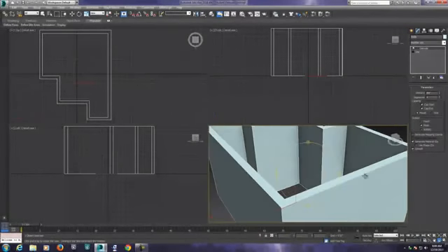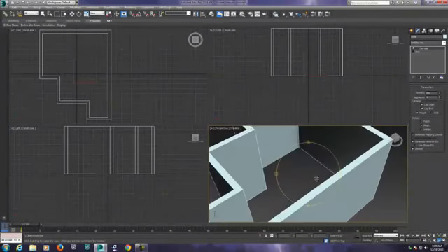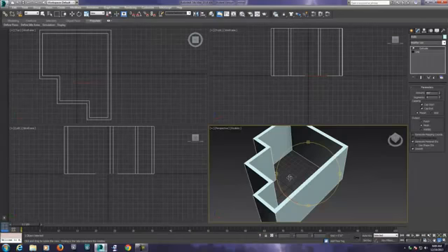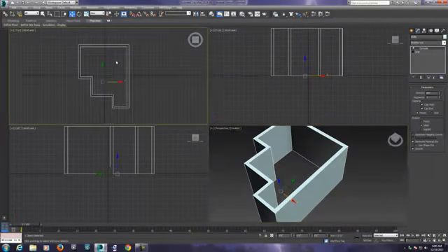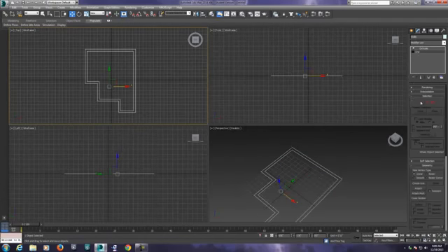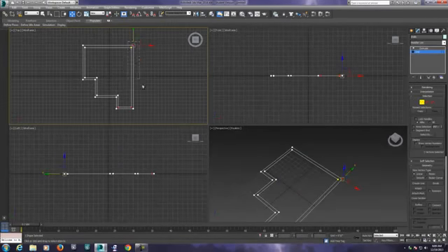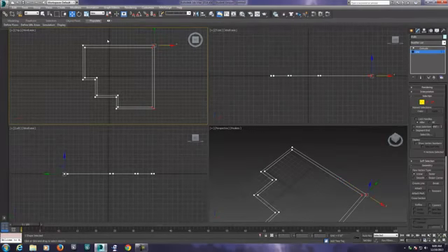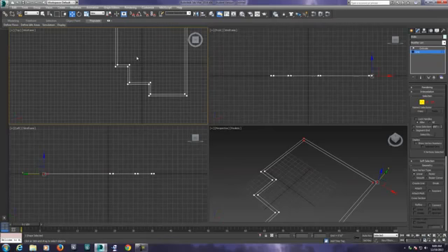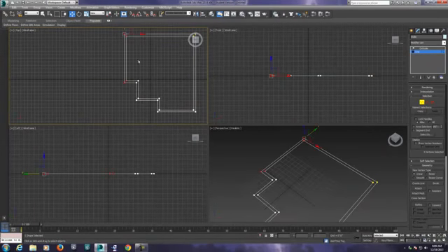Now you'll notice this is a very small room. And if your client has given you these dimensions, you may say, you know what, this is a very small room, I can't do much with it. That's okay. We can still have some fun. Back in the original line, we can make some more room. I'm going to select these vertices and stretch this part of the room out, and I'll stretch this part of the room out, and maybe I'll even take this wall over here some.